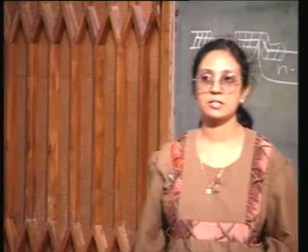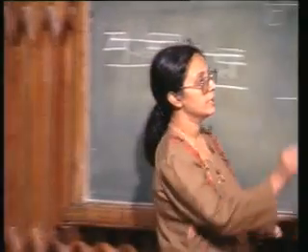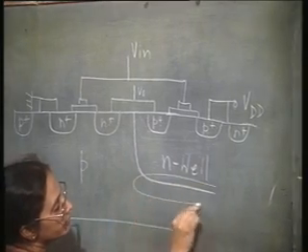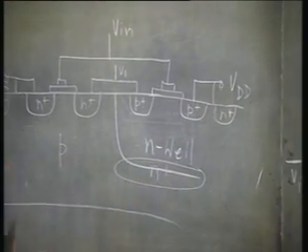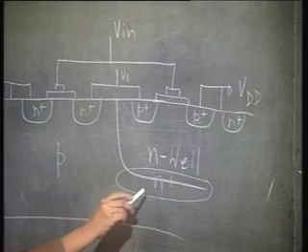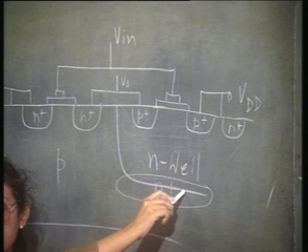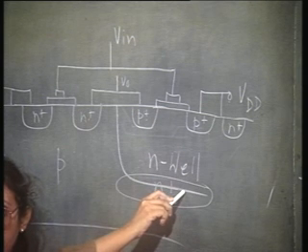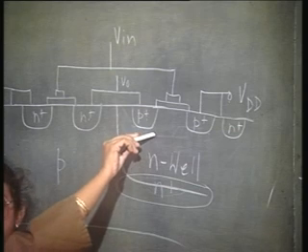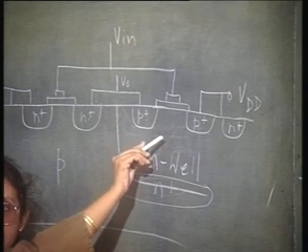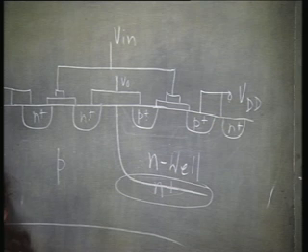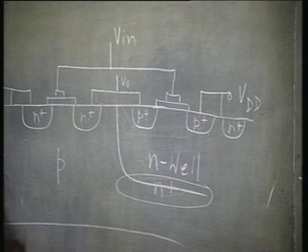In a retrograde structure you have buried layers, that is, if I can have an N plus region here, then the current will always flow through this, right. But as far as the depletion layer is concerned, you still see the low doping concentration of the Nwell. I am cutting down the shunt resistance path without actually affecting the doping concentration of the well.